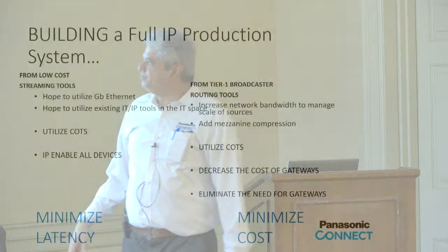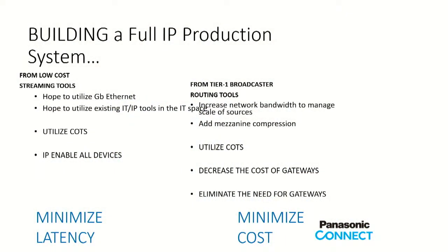So the second part was Gigabit Ethernet is now the minimum requirement for ST2110. If you're going 4K, then you do need 100 gig, even higher than that because of the bandwidth. We'll talk about it. And there are just standard tools available for software-based network management systems that are already there in the network world, so we can use those also.